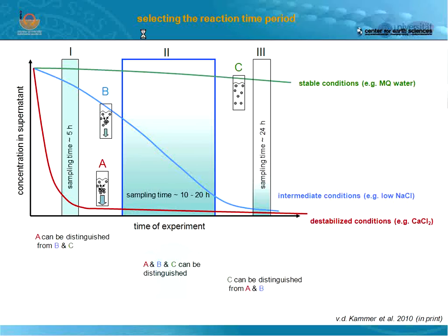It works quite well. So it's a turbidity measurement for the concentration. We are also backing this up with a calculated count rate in the Zetasizer, where we compare it as a kind of concentration measurement to the turbidity signal we get, and take the size and the zeta potential out of the Zetasizer measurements.